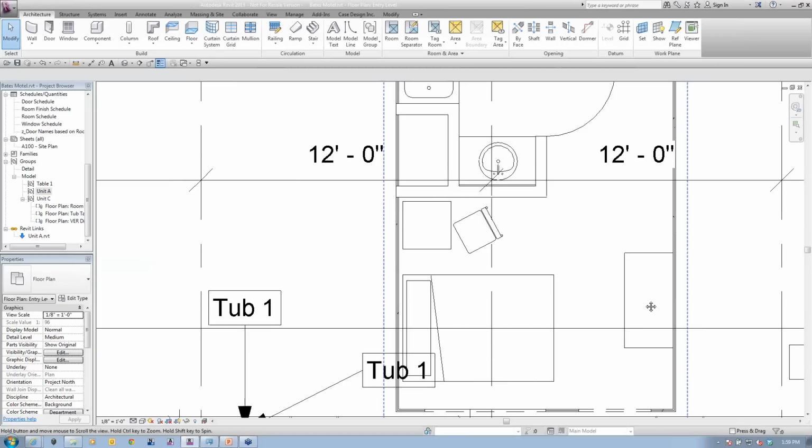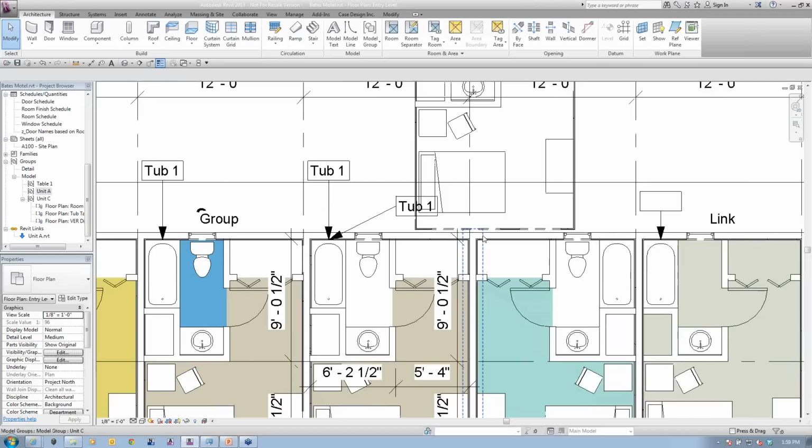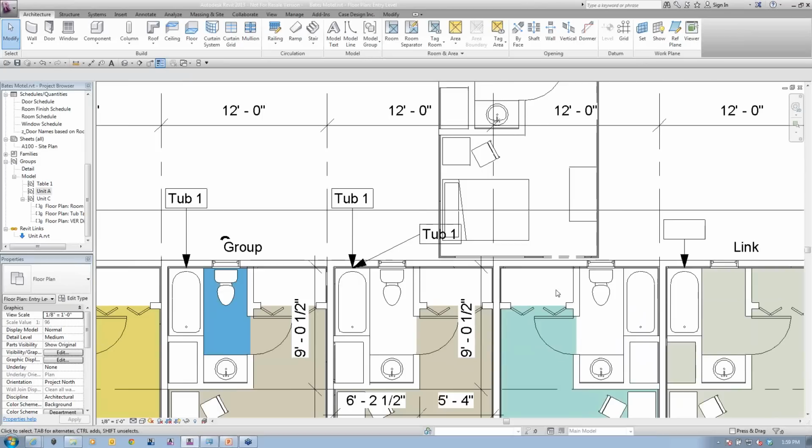And in addition to that, we put in openings that match the openings for the door and the windows that are in the room. So I've got a window in the back, and I'll have an opening in the back behind the water closet. And for the door and the window in the front, I put an opening in the same spot. It's a great way of doing that. I could have used the join command and joined the walls, but that's not going to work when I start turning this into links and things of that nature. So that's going to fail.